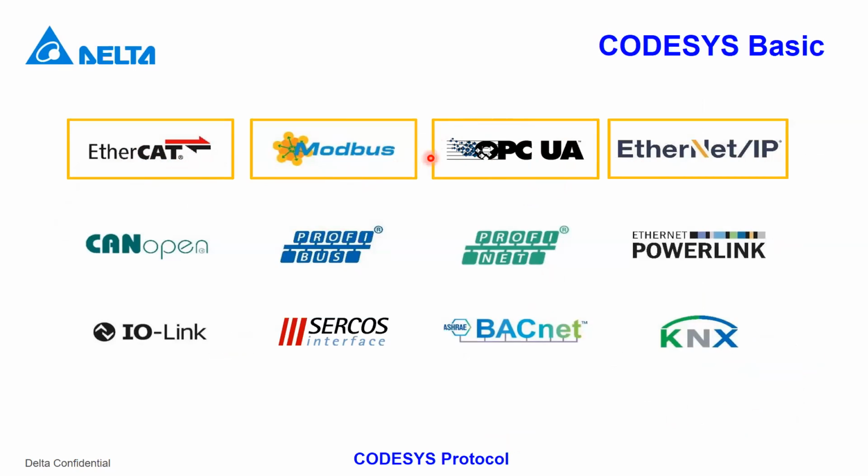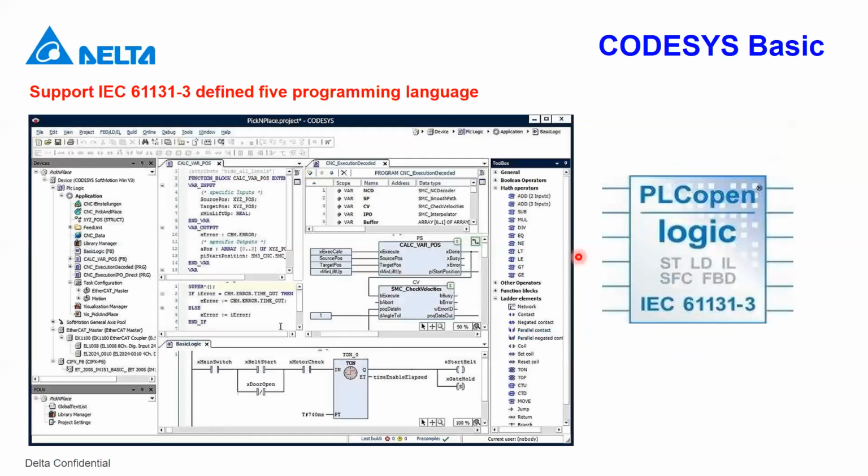And the AX series can also work as an OPC UA server. And in the future, for some AX models, it will also support Profinet. Okay, and this one, I think everyone knows that it supports IEC 61131. So you can see it supports languages like structured text, CFC.